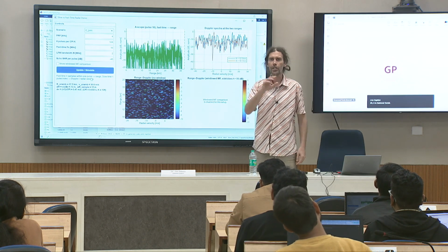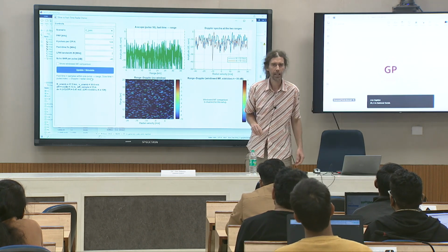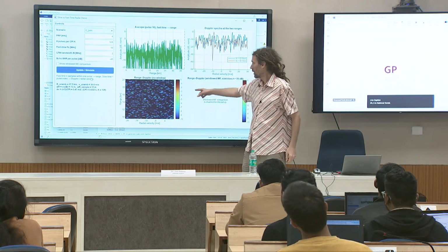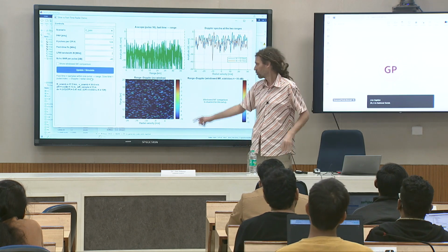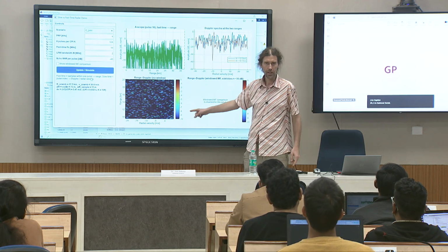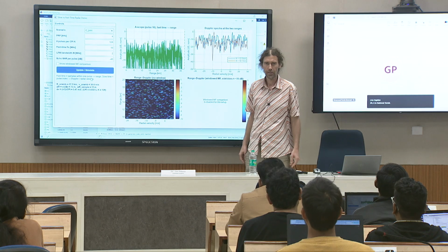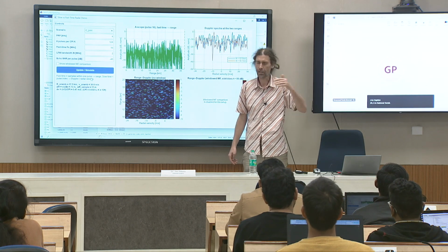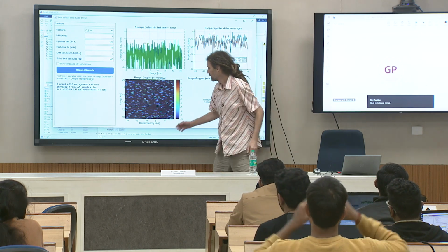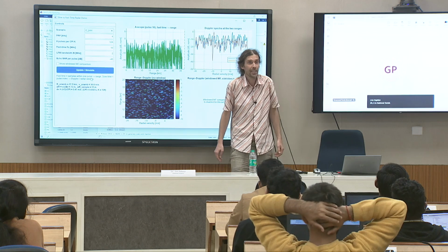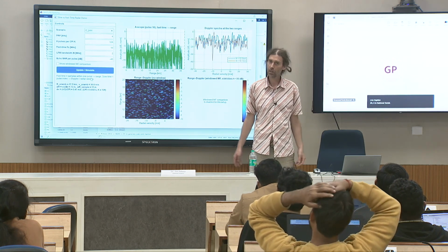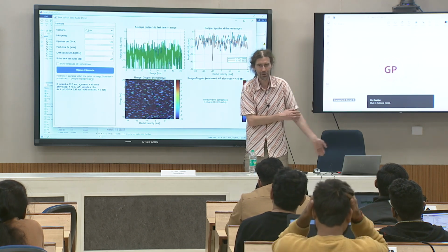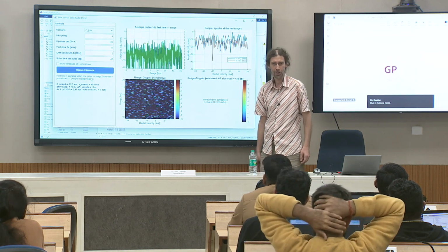And imagine, it is like before MTI, before removing static clutter, something like this. The raw radar data looks like this one. And from this, you need to find the target. For this reason, remove clutter by MTI, and then you will see, but it depends. If there is a small reflection, you will not see anything anyway. Of course, this is a school example, so real data are much more complex.